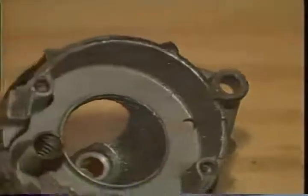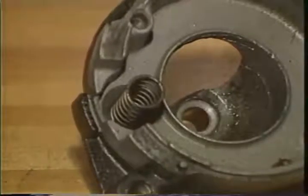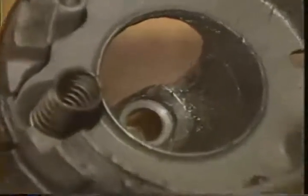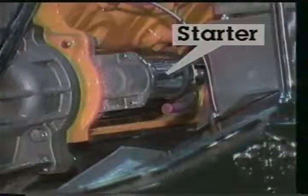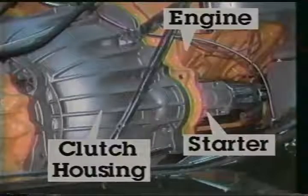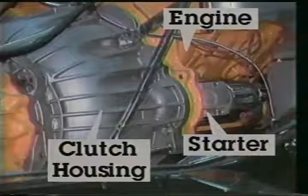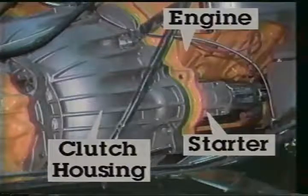Large holes in the thick drive end frame are provided for bolting the starting motor to the engine. An opening is provided so that the pinion gear can engage the flywheel ring gear. Here you see a starting motor attached to the side of the engine. The starter normally bolts to the engine block or to the clutch housing. A strong mounting of the starting motor is needed to keep the pinion gear and ring gear meshing quietly.